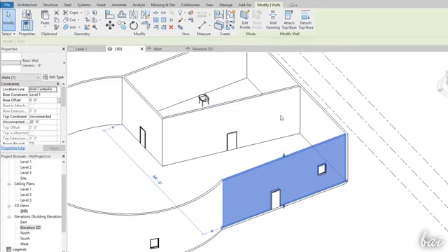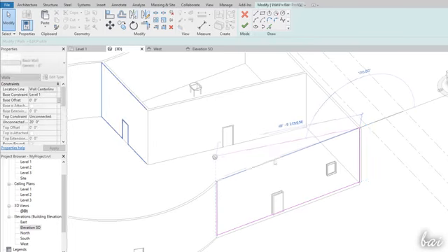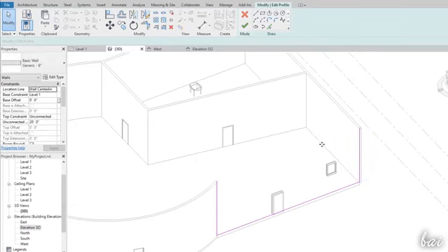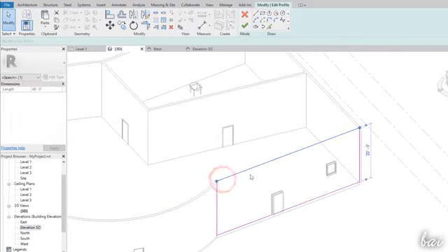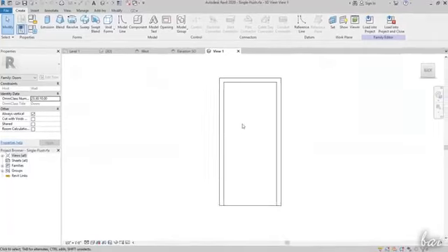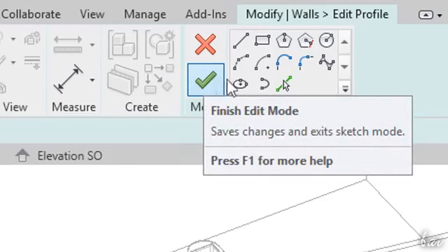You can use the Edit button under Mode to enter inside the Edit mode and change the object shape itself by editing any of its subcomponents, such as edges and vertices. In case of floors and walls, the Edit mode allows to change the basic shape by either using the line, the arc, and the polygon tools used to draw or moving each single side or vertex on the object. In case of families, you can use Edit Family to edit and customize their templates separately. To undo or apply your modifications, use Cancel or Finish Edit mode.